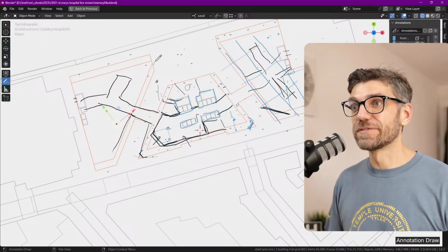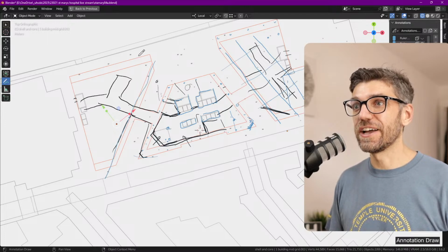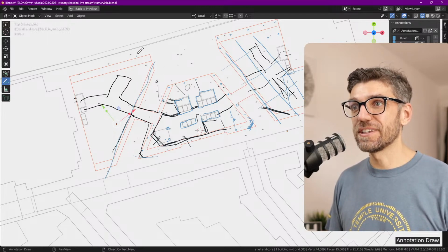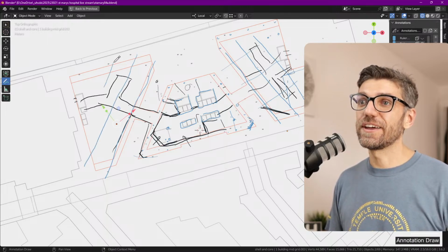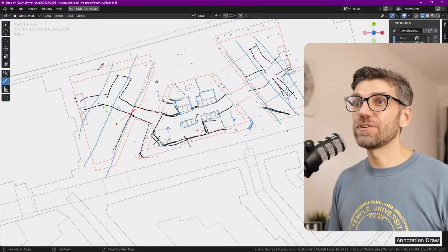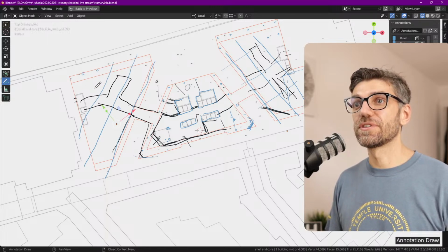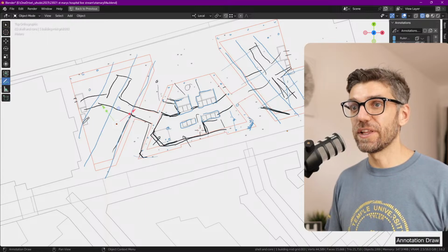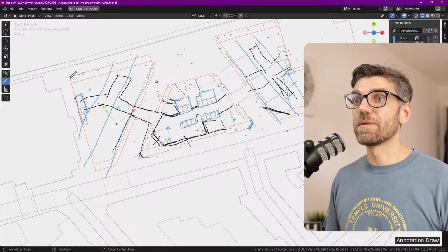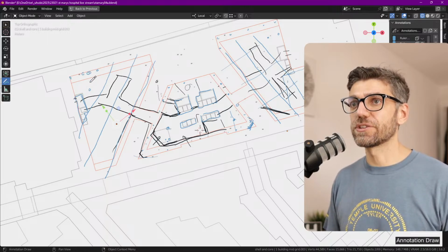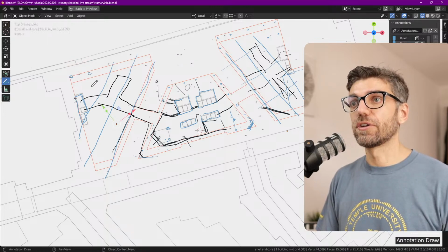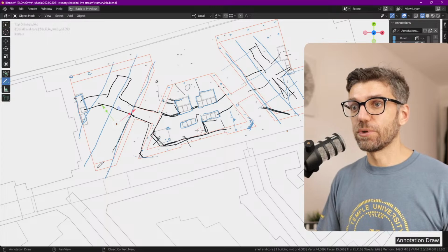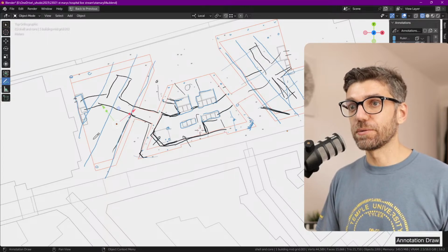So we have a column grid across this line here. Then I'm just looking at the spacing, so we probably end up somewhere over there. Then from there we might continue, and then we just have a couple of extra columns. Somewhere here, somewhere there, and then this core here works as a structural member as well. Maybe only two, actually, now that I'm looking at it. So a column here and a column there, and structure is sorted. We always need columns in the corners though, no matter what our structure is doing.